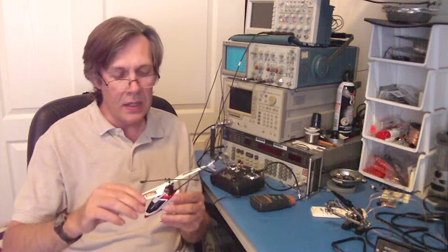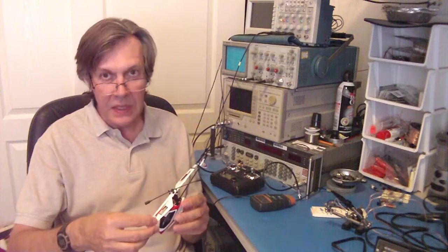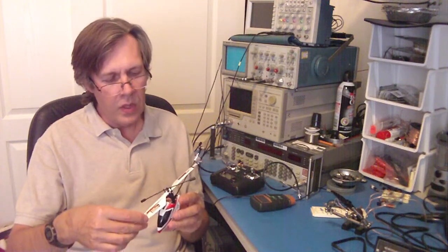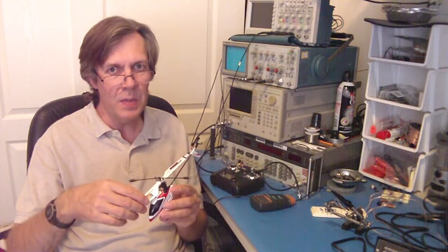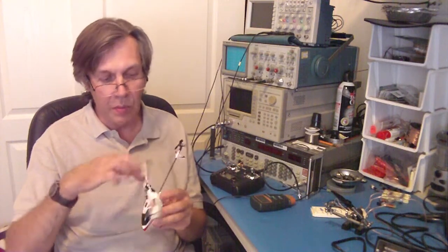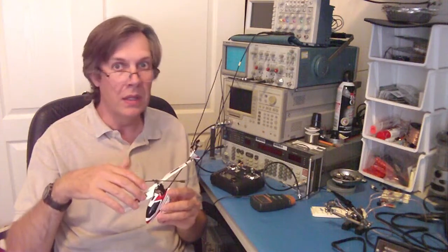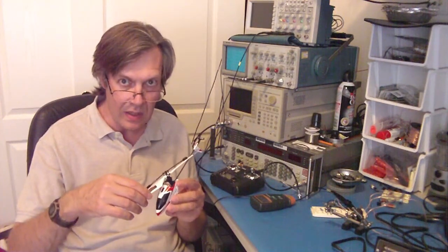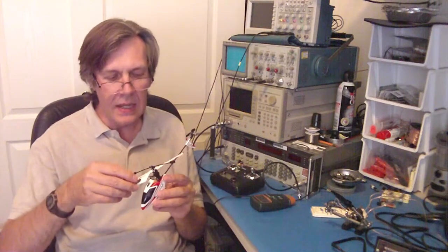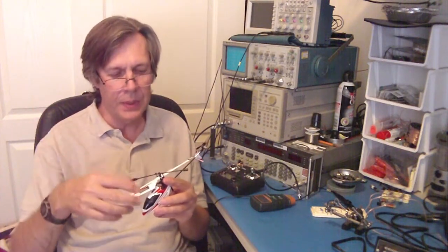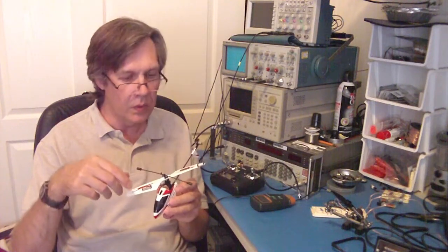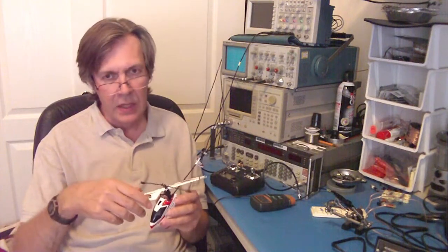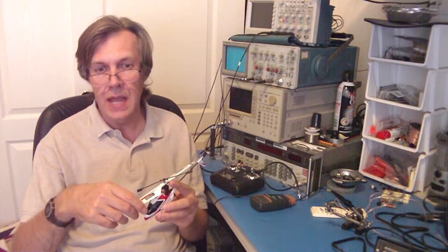So we just demonstrated with the strobe light sampling at 12.5 hertz that we saw the rotor appeared to be moving very slowly. Now, because the video camera samples a lot faster than that, we could also see the blur of the rotor moving, and so we knew that it actually wasn't moving at the slow rate that the strobe made it seem like. But if the strobe was your sampler, it would have appeared that the rotor was moving very slowly, either forwards or backwards, and we knew it was actually moving about 2 revolutions between each strobe sample. So that's a really good example of the aliasing.